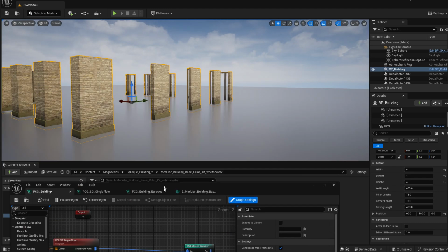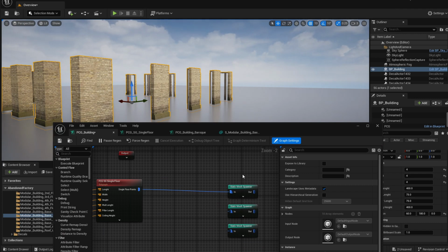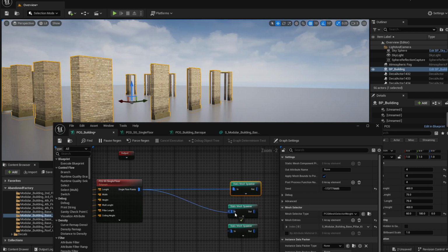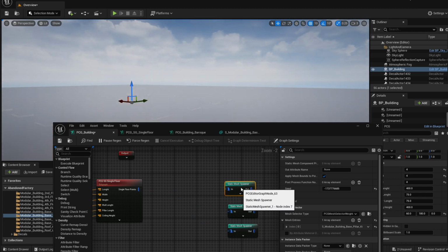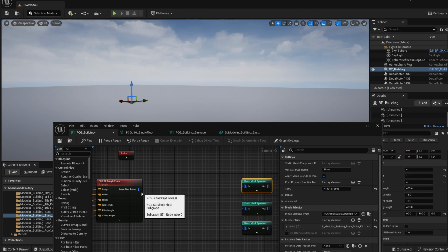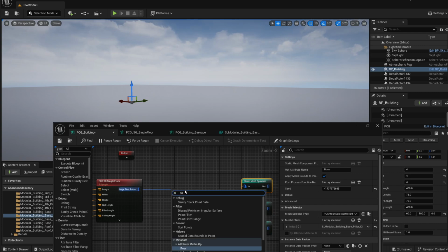points to any element, you see that for each point we are spawning the type of element into this static mesh spawner. We want to split them into all these three nodes, but we want only the corresponding points for each one to be used to place the type of element that we are defining for the different type of point. So let's do a point filter.